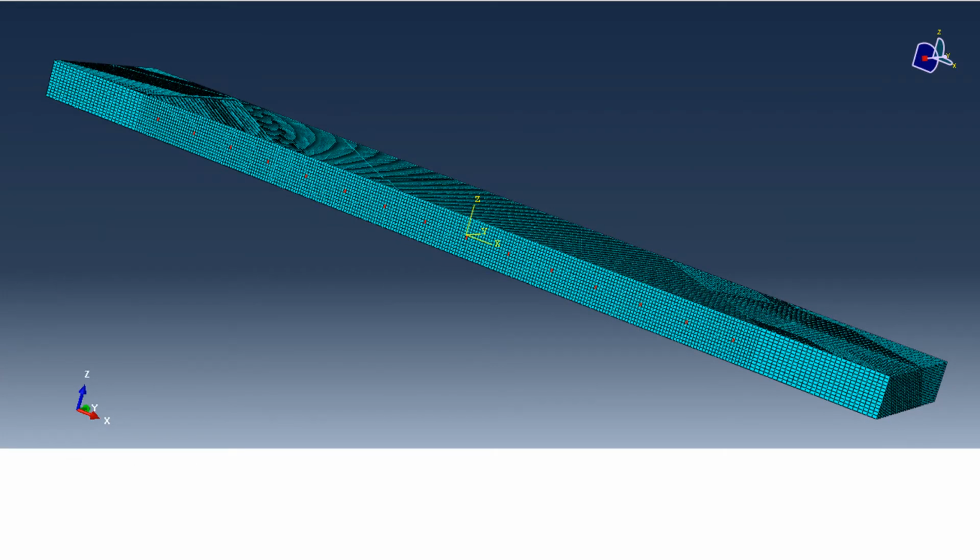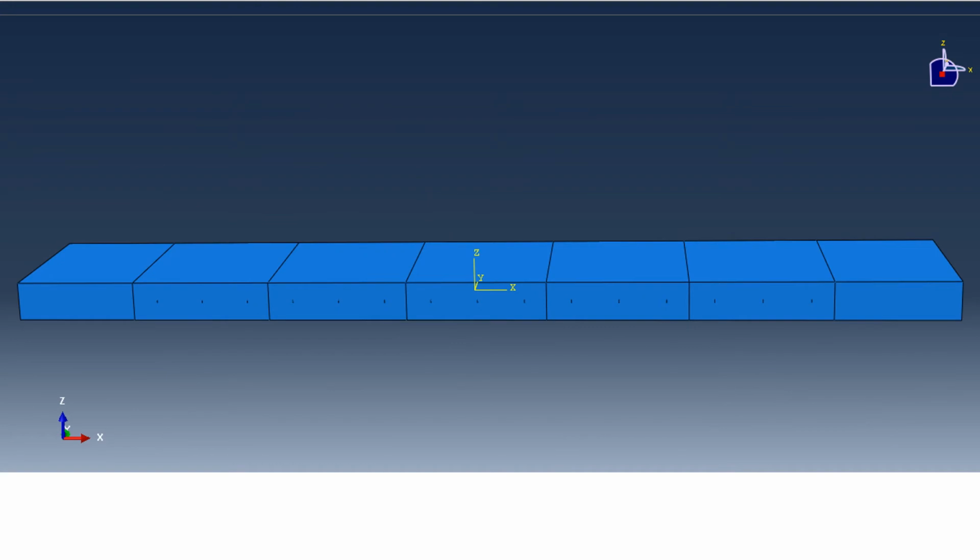We chose to model a field-scale reservoir in order to get an accurate look at how each stage, and each cluster individually, affects one another. Though this is computationally expensive, we chose to use reduced integration elements around the enrichment zone, as well as coarser mesh density in this region. Because we do not expect crack propagation in these regions, we assume this design choice will be beneficial.